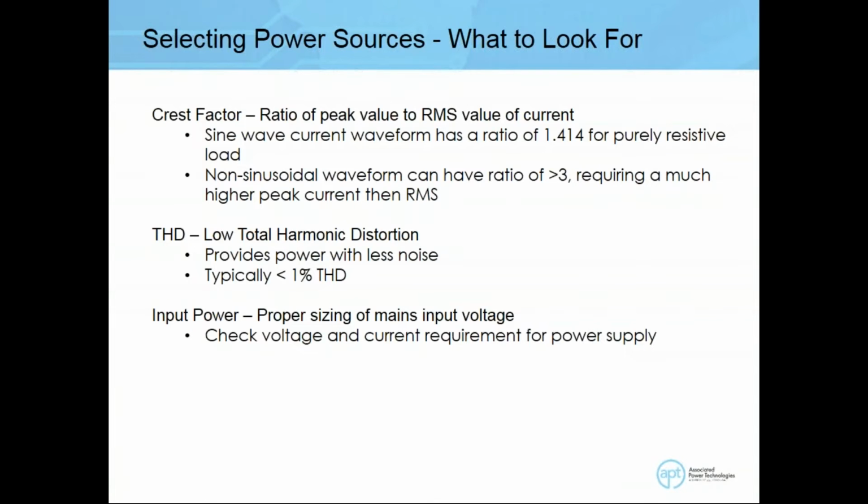A motor, an inductor, some kind of combination of a heating element with some other motor in there, it may require you to have a non-ideal sine wave. Is a power supply able to handle these crest factors? A pure sine wave has a crest factor of 1.414. Now, this crest factor could go as high as 3 or more for some of these loads that are connected to a power supply. So you want to make sure that the crest factor is addressed in your product specification.